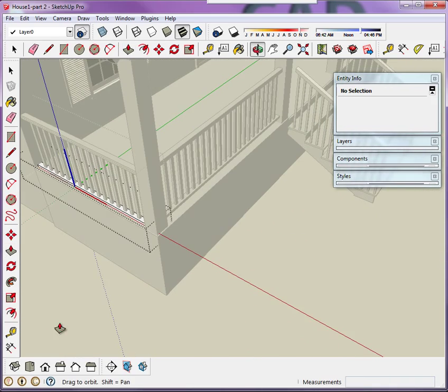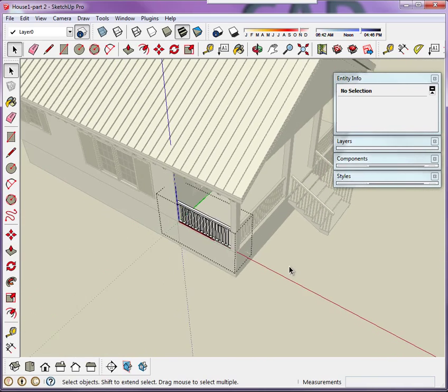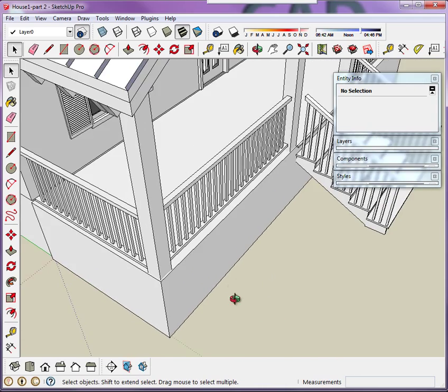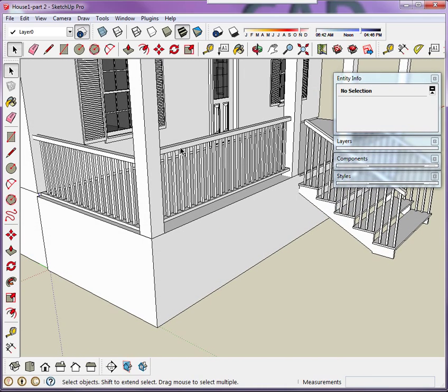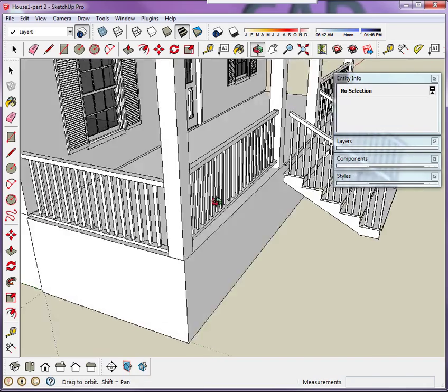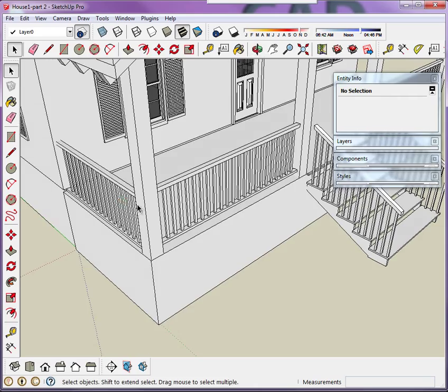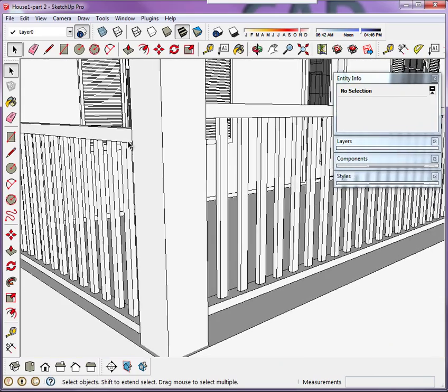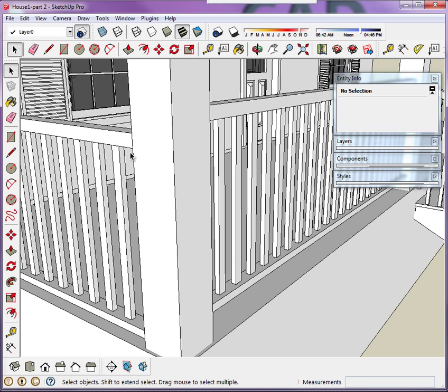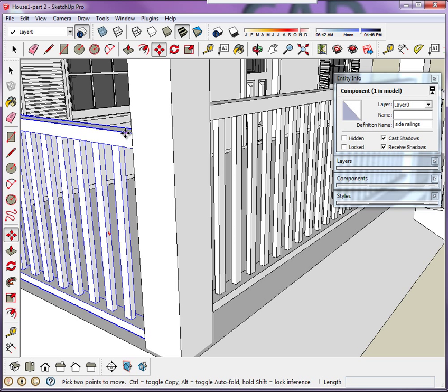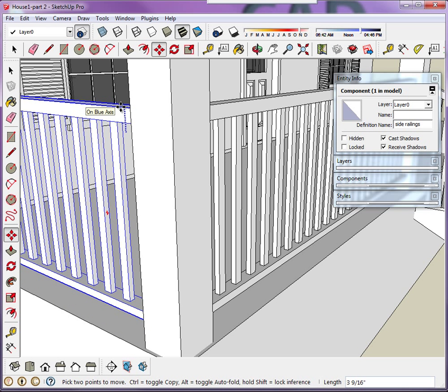Now, if I exit the component entirely, right? Now you can see, without affecting these railings, I was able to recreate a separate, unique railing based on the components that make up this railing. So now I can spend the time to correctly size them or position them, and here it's just going to be a matter of selecting the one component and moving up along the Z-axis, right? Shift and look at this, right? Now I can just snap to the top face there.